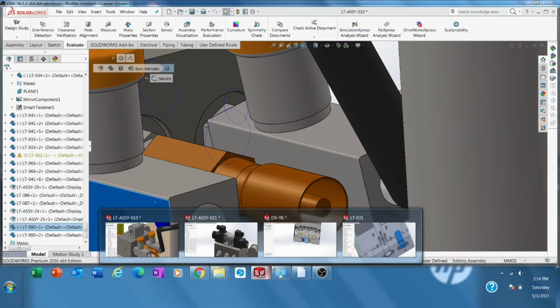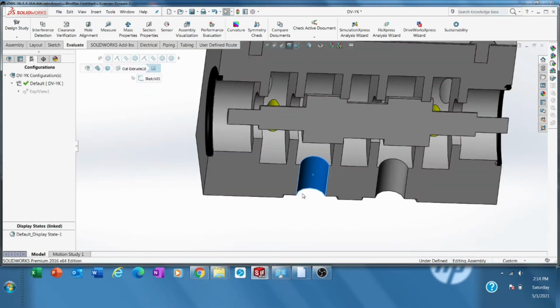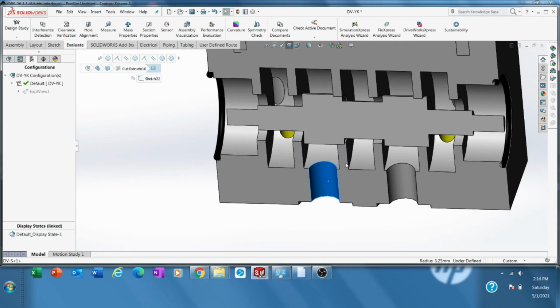Okay, that's when you want to open this port. So it will be open as long as what you need, but it will shut down based on your system. Maybe when you hit proximity, the electricity to the coil will be shut down, and then it will move back again to the closed center, because we have a spring here, as I showed in the exploded view. That will make it move to its original position. So okay, that's already flowing to that direction.